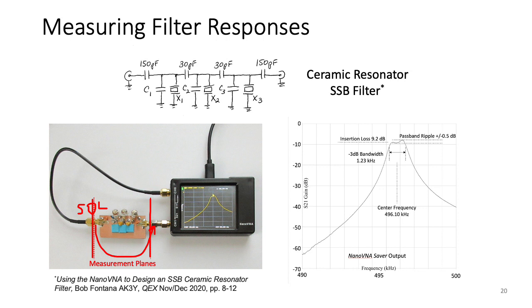In doing so, that gets rid of all the effects of this little cable, this little connector here, this coaxial cable run, this connector, and also this barrel. That's important. Less so at very low frequencies, very important at UHF, VHF, and certainly higher microwave frequencies. In this case, the filter was swept between 490 and 500 kilohertz, and you see the results here.